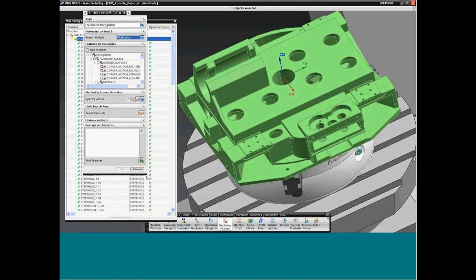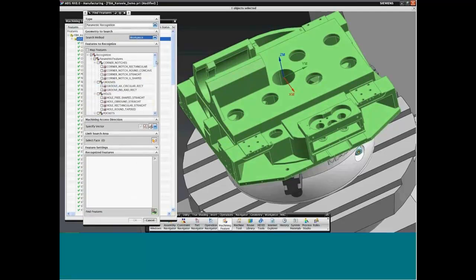And then, let's open this dialog box so we can see a little bit more. Then you can see these are the 60 or so types of features that NX will recognise out of the box. The names of the features can be defined, and you can obviously choose whichever features you wish to find in one go, or you can find them all at the same time.